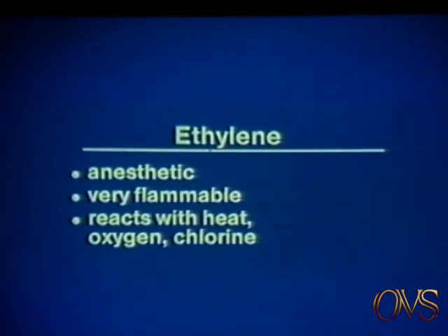Ethylene has been known to decompose within a pipeline under pressure shock, and above ground, ethylene lines should be insulated for protection from grass fires or other localized heat sources. Ethylene gas, however, is slightly lighter than air, so the vapors tend not to collect in low spots.